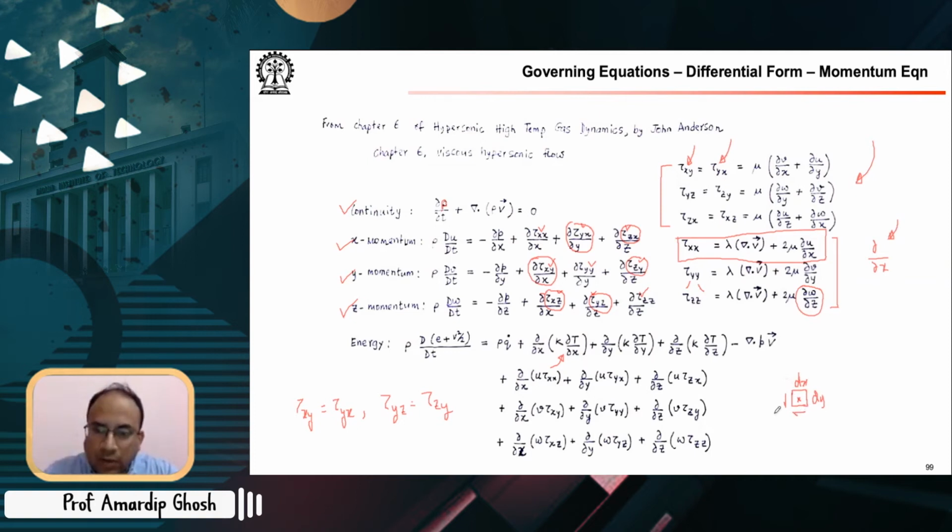However, if you have a situation where the moment doesn't become 0, say around the centroid, it doesn't really matter. You can take it around the centroid, or around this point by using the parallel axis theorem, etc. But because your delta x, or dx, and these are small numbers, in the expression for the moment of inertia the product with alpha becomes 0. So typically you end up with just these shear stresses being the same.